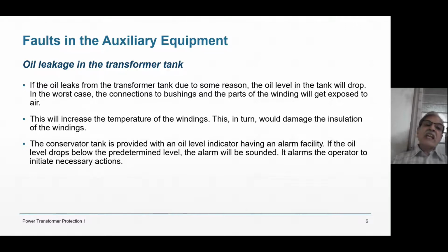So oil leakage is not an electrical thing. You see, no electrical relay will be able to sense the oil leakage. For that, we have a Buchholz relay which we are going to see, right? The Buchholz relay is used. It is connected between transformer tank and conservator tank.